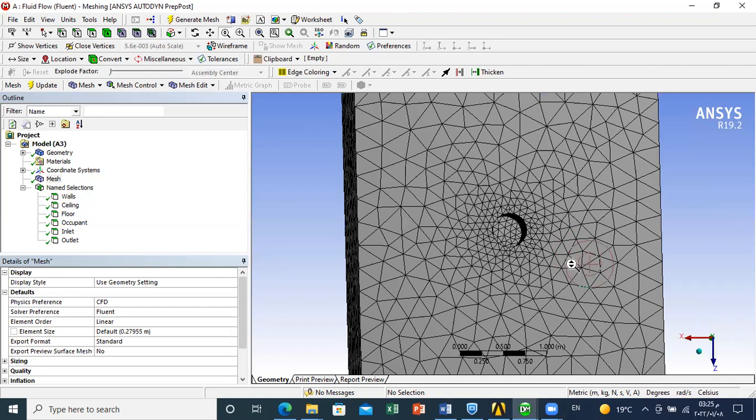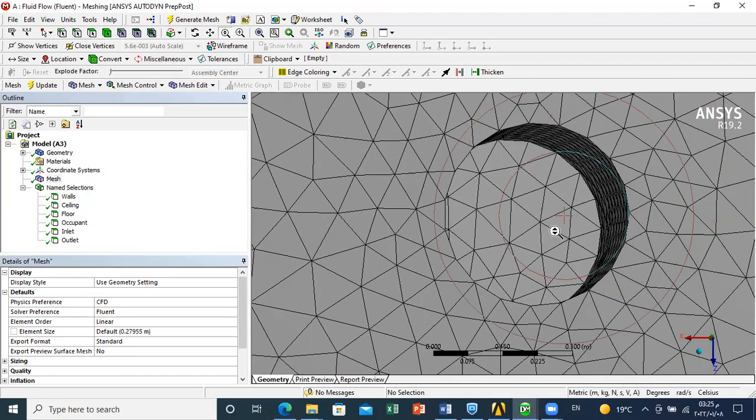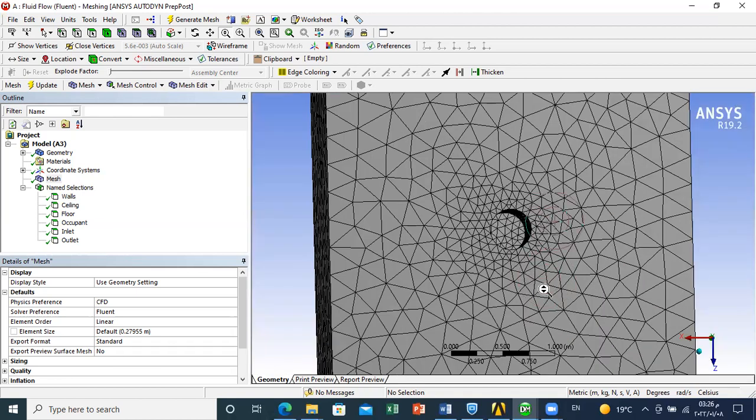So in general, tetrahedral elements are used when you have curves, because they will allow you to capture your curves in a more efficient way than rectangular meshing. For a rectangular mesh, you don't have straight lines and you don't have right angles to do it. So it will not be efficient to use a rectangular mesh when you have curves. This is why tetrahedral elements are more efficient in such a case. And now, how to change the mesh settings, and what strategies can be used to enhance the mesh quality? This is what will be done now.